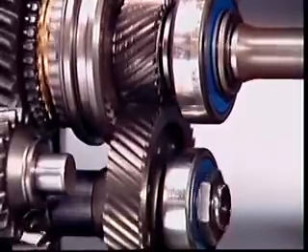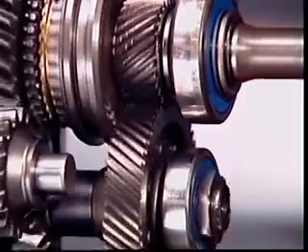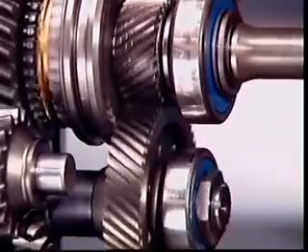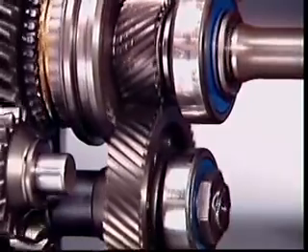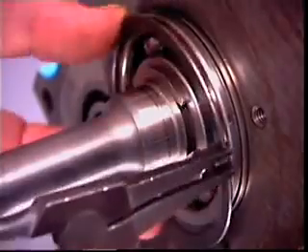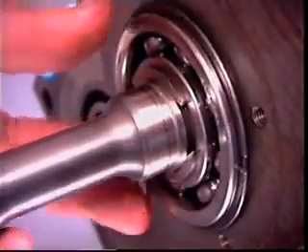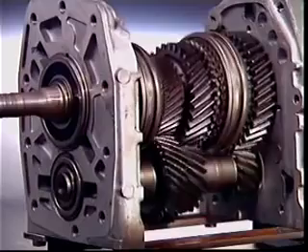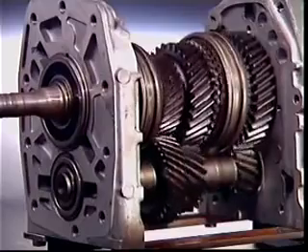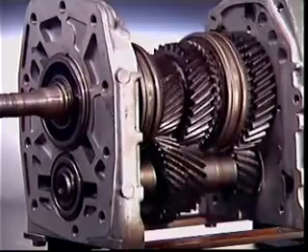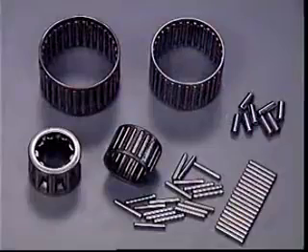The helical gearing creates radial and thrust loads as the gears try to force each other apart and move endwise. A circlip in a groove on the outside of the bearing can locate each shaft in the casing and maintain the alignment of the gears and engagement hubs.